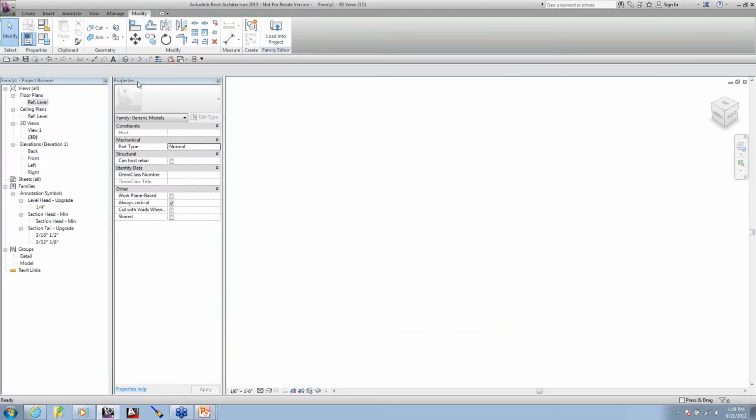And I'm not sure if you guys know this, but if you don't look at the view perpendicular, and you have to be in an elevation section or floor plan view or ceiling plan view, you can't see the reference plane. So we'll never see a reference plane in 3D. However, I can do a work plane in 3D.